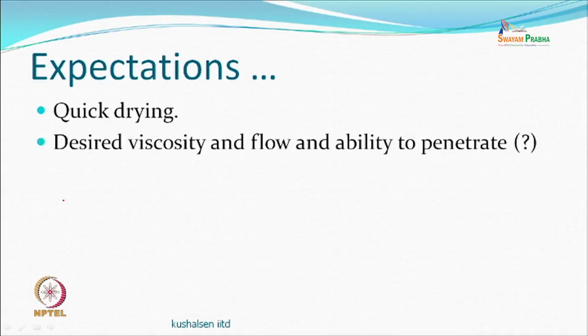This is what we just talked about, that they should have a desired viscosity, which we sometimes call a printable viscosity, and a flow. So, let us say a screen has a paste and you lift the screen, the paste does not come down, because if that was true, then it will keep dripping. So, when does it come down? When you put a squeegee, otherwise it does not come down.